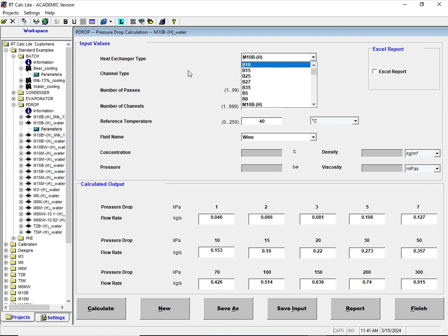In other words, you can actually predict the heat transfer and the pressure drop. And then what you then do is you compare and you calibrate against some of the industry standard plates from the OEM, for instance, or other sources that you know. And then you can further adjust until you get the thing bang on at certain calibration points. Now, it's the only software that I know that you can actually do that.